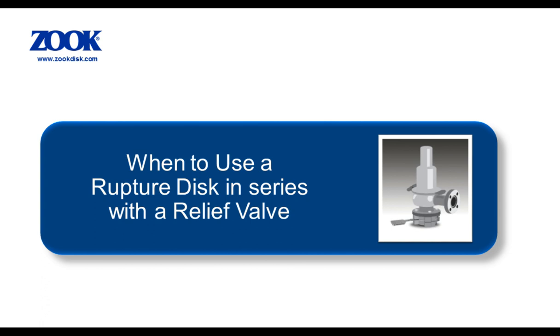A common application is actually to use a rupture disk in series with a relief valve. In this case, the disk is placed below or in front of the valve, in essence isolating the valve from the process. The inexpensive rupture disk is the only thing exposed to the process until an actual overpressure occurs. This is extremely advantageous in highly corrosive applications. This combines the advantages of a fast-acting, leak-tight rupture disk below and the reclosing functionality of the valve above.